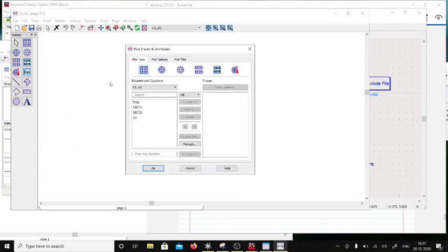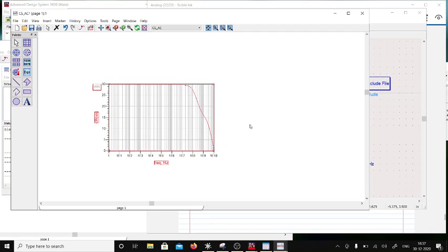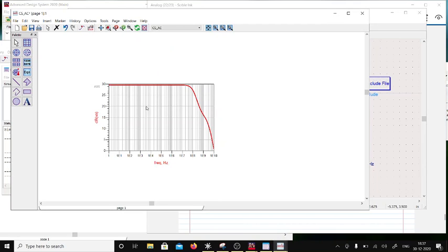and then I'm going to plot VO in dB. So that would be the gain, and then I will put the axis to be a log axis. Okay, so now what you see here is a familiar Bode plot. So this is your near to 30. So we figured out from our equation it was 25.26 dB gain. It turns out to be 29.